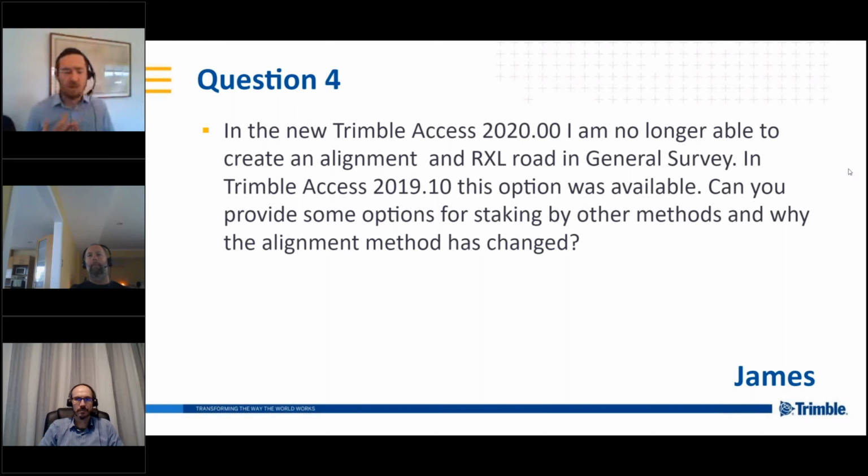And if you're very keen, you can also key in to operate a manual total station, which instead of taking a measurement and getting the feedback from an instrument, you would key in the azimuth, vertical and slope distance that the instrument would usually supply.